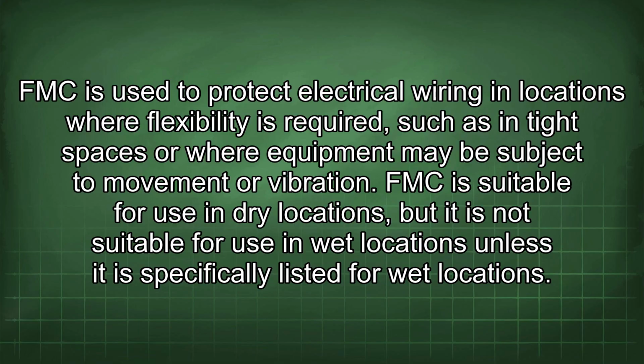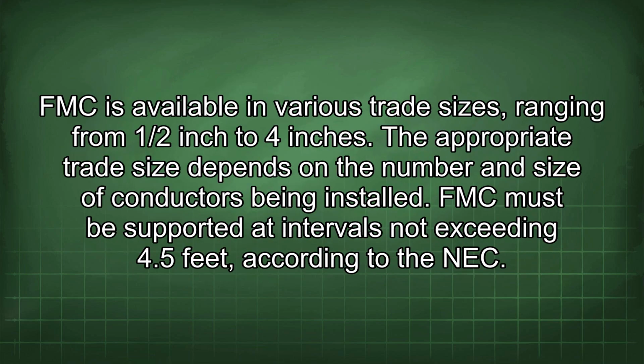FMC is suitable for use in dry locations, but it is not suitable for use in wet locations unless it is specifically listed for wet locations. FMC is available in various trade sizes ranging from 1/2 inch to 4 inches. The appropriate trade size depends on the number and size of conductors being installed.